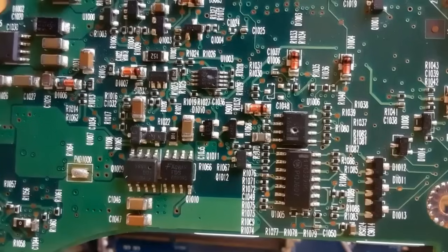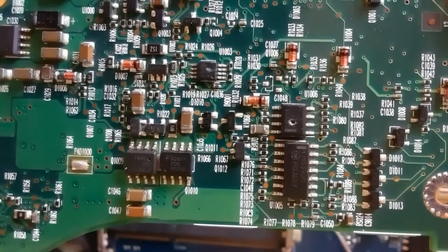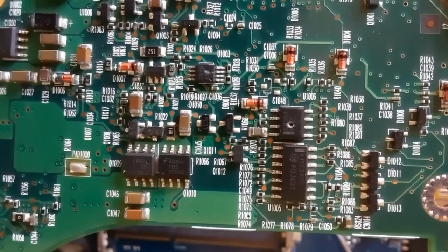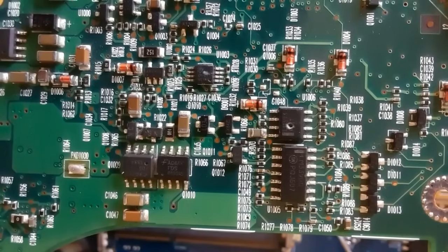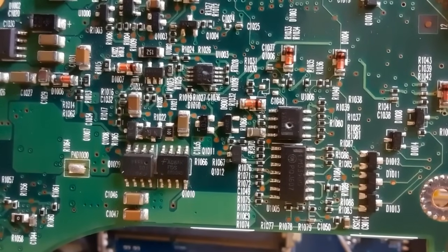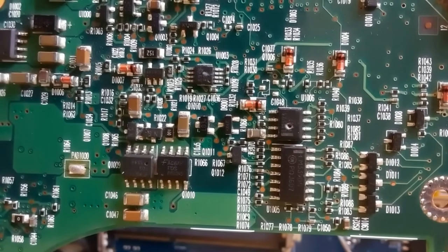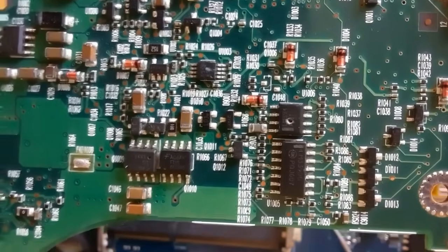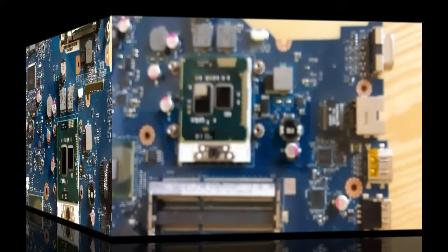So that's why you should always begin with a visual inspection, because if you have an IC like this, you should change it automatically. But if you don't do a visual inspection, you can just make measurements and check from here to here without finding the problem. So that's why the visual inspection is a very important step before doing anything.